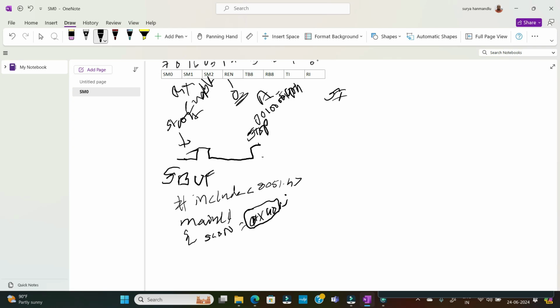Then we have to select a timer, and the timer is selected by using a register called TMOD, which I already kept in my 8051 programming playlist. You can go through that. It also has 8 flags, like SCON. The first flag is the gate bit, the second flag is C/T bar, and the third and fourth are M1, M0. Similarly, the rest of the 4 flags are the same. So it's very easy to learn TMOD.